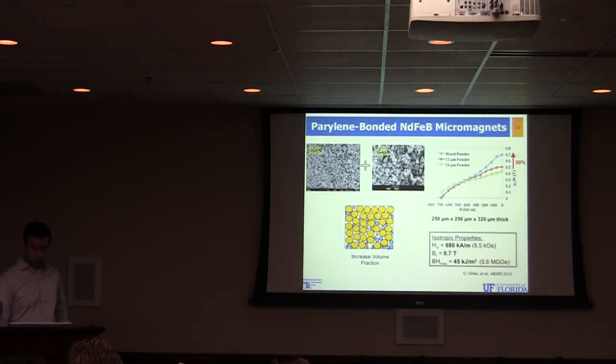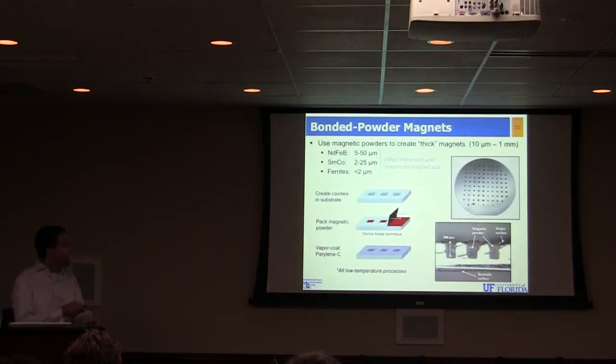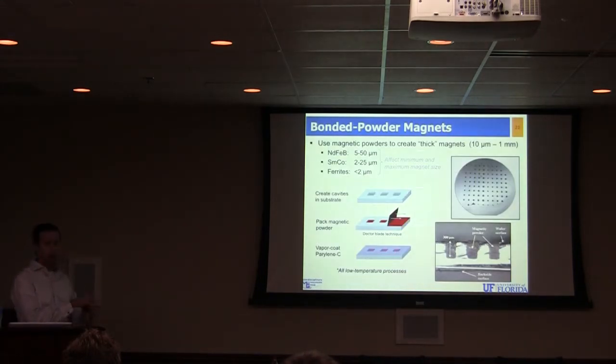Yep. So your surface looked very clean after that, Dr. Blade. Do you do any cleaning after? Sometimes we leave the photoresist on from the DRIE, and we can strip that off, and it helps lift off the particles. These very large 50 micron particles actually transfer very cleanly. They're pretty big. The 15 micron is also pretty clean. So this is not a doctored photo, that's just what it looks like. But I will say this is actually the rough side of the wafer. This is the back side of the wafer. That's why it's not a dull finish and not a shiny finish.